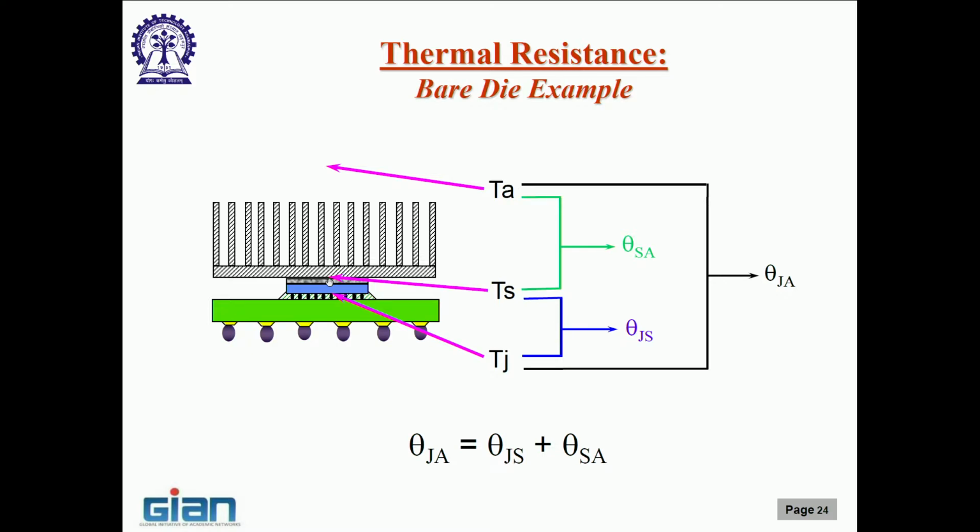Granted that the thermal resistance that I measure has contributions from the silicon, from the base of the heat sink and so on, but these are going to be there. So, if I see a reduction by an X amount, that must be due to the interface material, a little bit of give and take, a little bit here and there. Okay.